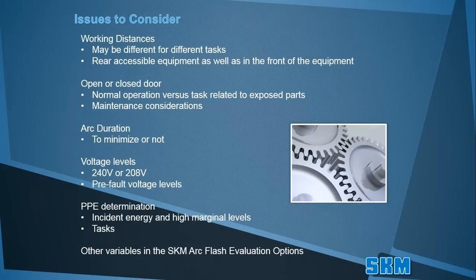Here are some Arc Flash issues to consider: working distance, open or closed door, arc duration, voltage levels, PPE determination. There are other options in the SKM Arc Flash Evaluation that can affect your results. Those will be covered in a separate video.